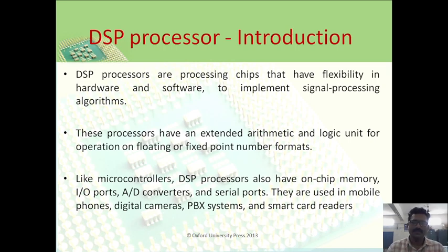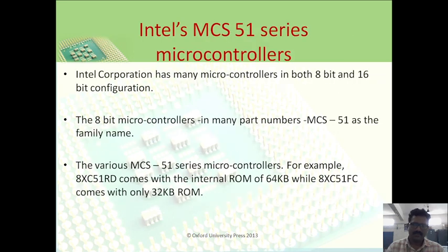Coming to DSP processors, these are digital signal processing chips that have flexibility in hardware and software to implement signal processing. These processors have an extended arithmetic and logic unit for floating and fixed point number operations. Like microcontrollers, DSP processors also have on-chip memory, IO ports, A to D converters and serial ports. They are used in mobile phones, digital cameras, PBX systems and smart card readers.